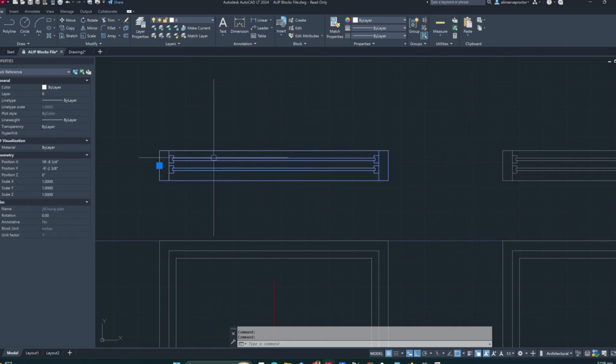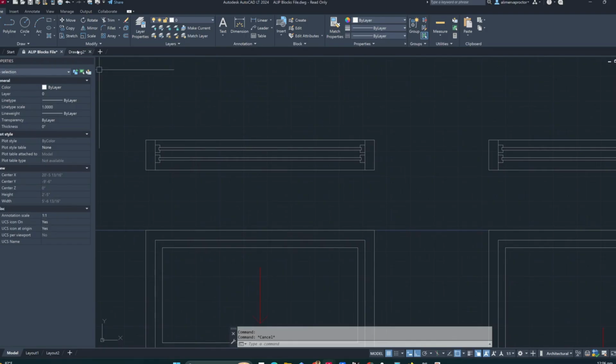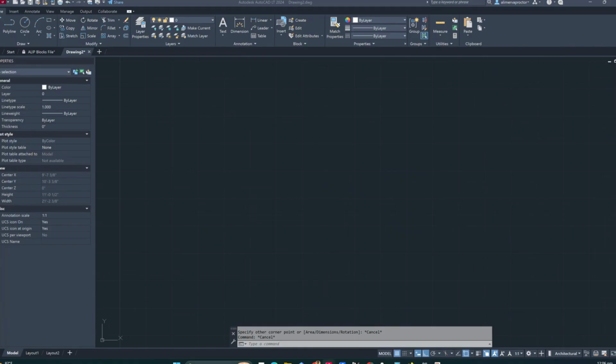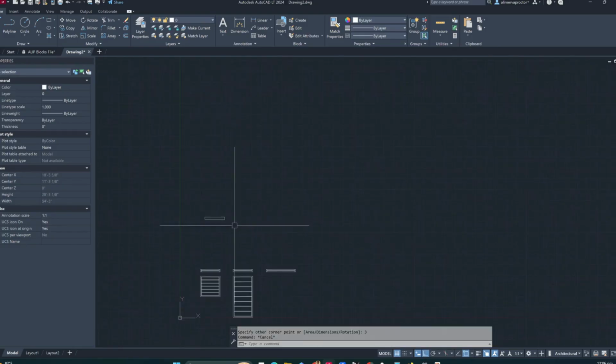So this is how this window is gonna look. This might be a little complex, right? So we might go step by step, and then you guys will have to go back in and technically rewatch the videos to get it done, right? So this is what we did before. We're gonna draw a rectangle, right? Same rectangle that we're drawing with the same space, the 2 feet by 3 inches. So REC, enter, 2 feet tab, 3, enter, right?